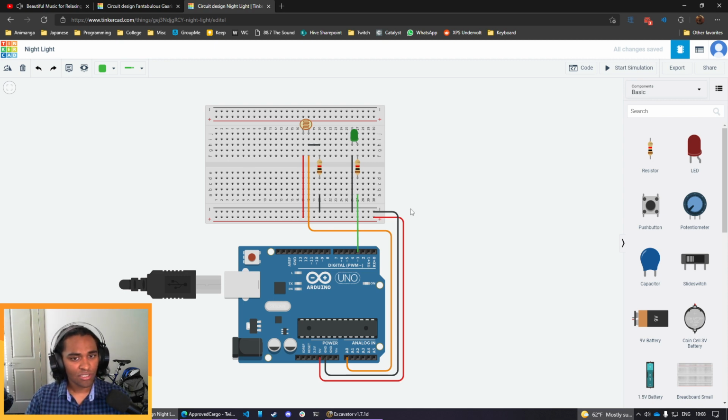But yeah, if there are no questions, the next thing I want to talk about is the pin selection on the Arduino. Check out our digital PWM section here. You see how it's labeled digital PWM? I'm hovering my mouse over it. This section is a selection of pins that can output either a high signal or a low signal. If you're familiar with electrical terms, it's a high voltage or a low voltage. If you're more familiar with software, it's a binary 1 or a binary 0. So it's an either you get it or you don't situation, right?